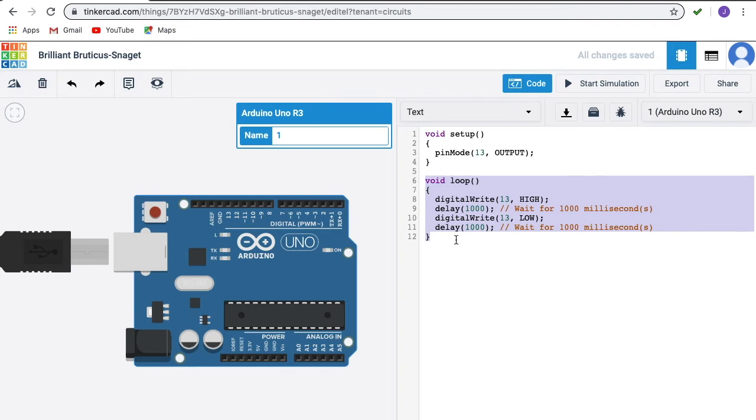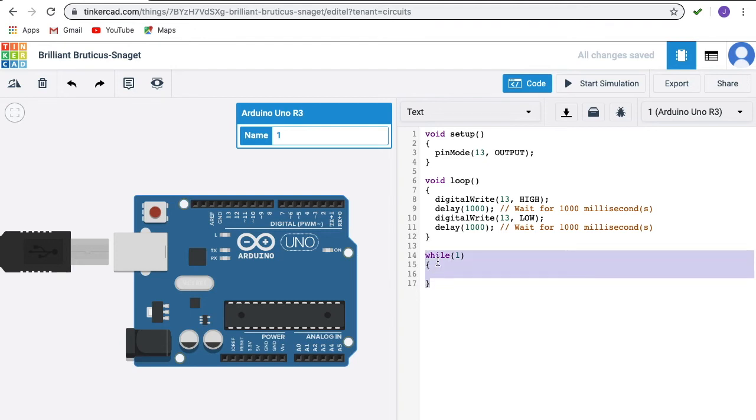It is similar to what in C language we used to write as a while(1) loop, forever loop, or always loop. It is called in a different way here. The purpose of this loop is that the while(1) condition will always be true, so the statements we write inside this loop will execute always.